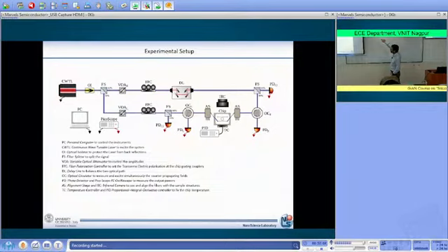The light now goes this way, reaches this AS, what is AS? Alignment stage. It arrives at this alignment stage, and then is inserted into the microring resonator. Then you may have some reflection of light from the microring resonator, and the reflected light comes out from here and reaches the optical circulator at port 2.